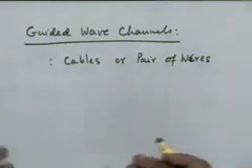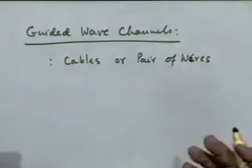A cable, you normally look upon the cable or a pair of wires as if they are carrying current, and we talk about voltages and currents, but basically you are transmitting electromagnetic waves, right? Depending on whether you are working at a lower frequency or a higher frequency, you can treat them as lumped circuit representations, otherwise you can't represent them. You have to work with them in terms of EM propagation. If they become transmission lines, right? We don't call them just circuits anymore. A pair of wires may look like a circuit, right?